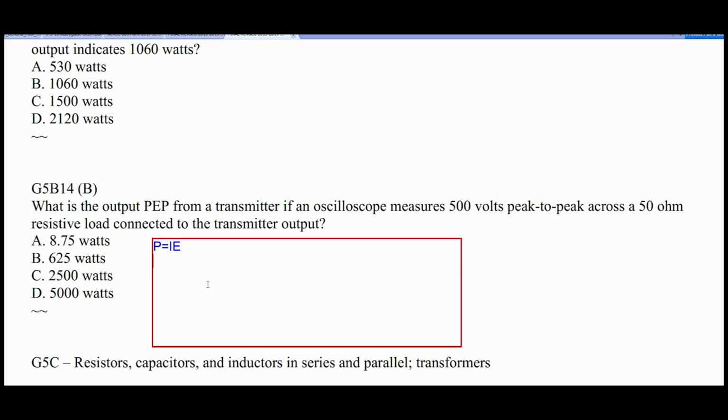And we've got to determine what the voltage is, and that's where this gets tricky. So it's 500 volts, and we divide it in half because we want to take just half the cycle. So we've got 250 volts to work with times root mean squared, so times 0.707, and that equals some number.